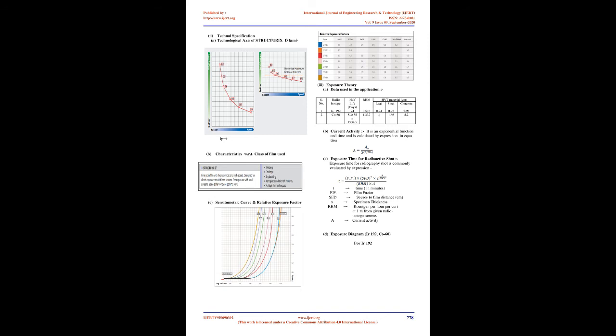The slump for high-density aggregate mixtures should normally be between 40 and 75 mm. It is far more susceptible to variations in quality due to improper handling. Concrete should be placed in layers not more than 30 mm thick. The concrete should be free of segregation and voids. Higher frequency vibration causes segregation of high-density aggregates by settlement, i.e. large aggregate migrates to the bottom of the element. The radius of action of vibrators used in HDC is less effective.